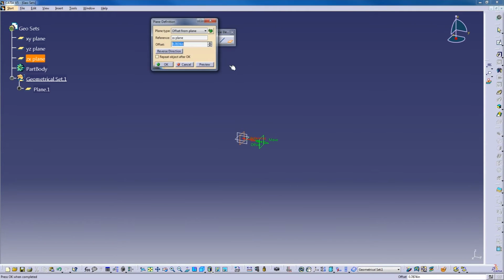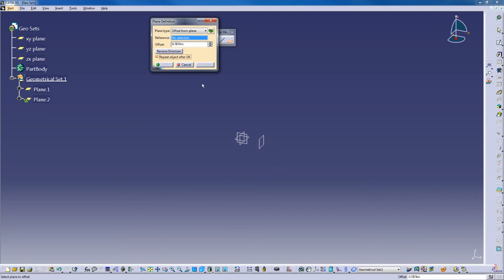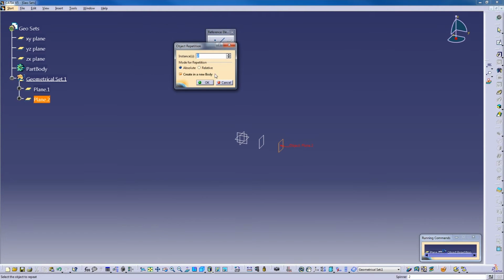Alright, so I can pick the planes tool and I can say I want a plane right here, and I can keep going with this. In the other videos we've learned that we can continue this on, and we can add multiples of these. So I can say add 10 if I want. By the way, I'm unchecking new body so it doesn't create another folder inside there.